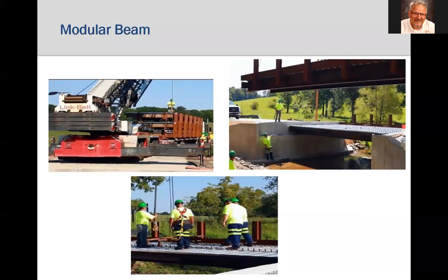The new bridge was built with 3 modular sections that were shipped on 1 truck to the site. The modular sections consisted of 2 weathering steel rolled beams with a pre-attached corrugated metal deck. Bolted diaphragms connected the beam pair modules after they were set on the abutments. The concrete deck was cast in place and a galvanized steel railing finished the bridge.